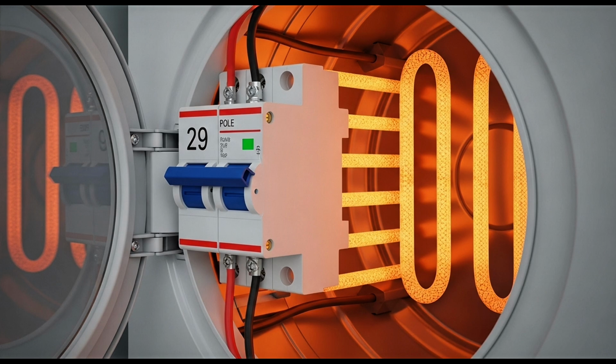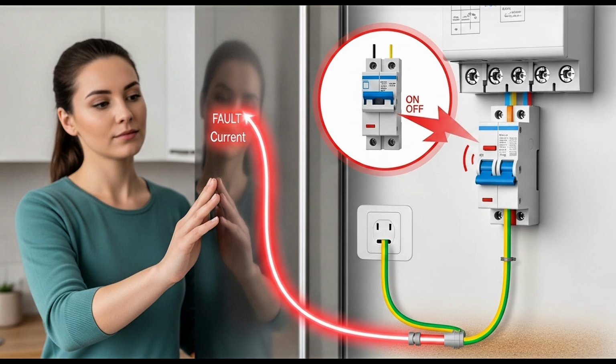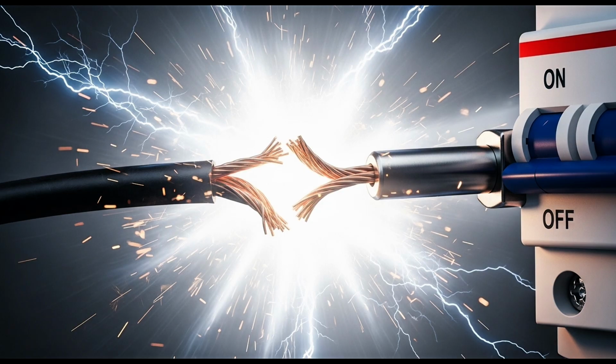The ground bar, often green or bare copper, provides a safety path for fault currents. All the bare copper or green grounding wires from the circuits connect here. If a hot wire ever touches a metal electrical box or appliance frame, the ground wire provides a low-resistance path that causes the breaker to trip immediately, rather than leaving the metal surface energized and dangerous.